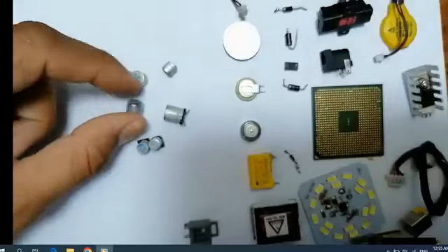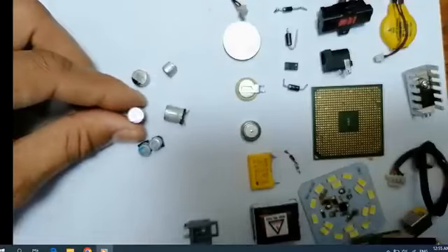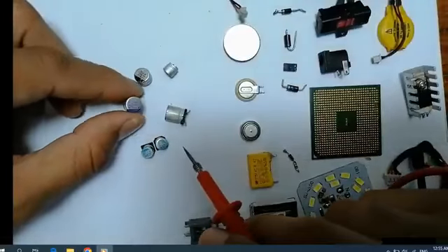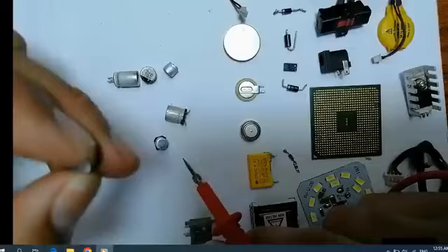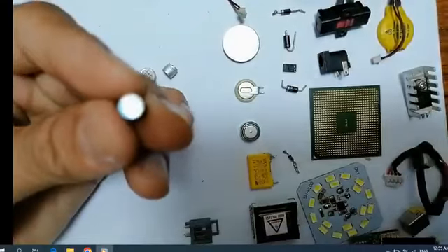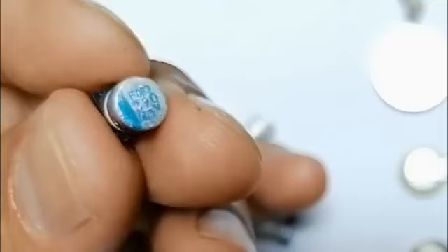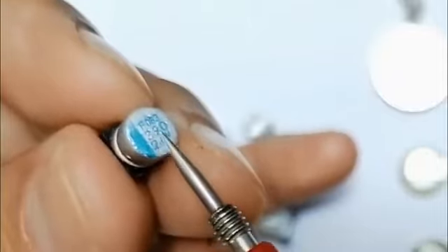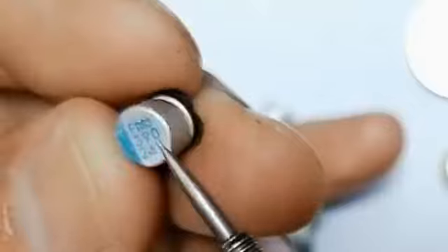Over here we have an electrolytic capacitor or chemical capacitor. This is another type of electrolytic capacitor. We can call it SMD capacitors. We find this kind of capacitor in the computer motherboard and also in the laptop motherboard, okay? Basically it has two characteristics, the voltage and the unit in farad. For example, this one is 390 microfarad and 25 volt, okay? And of course it has two terminals, negative terminal and positive terminal.